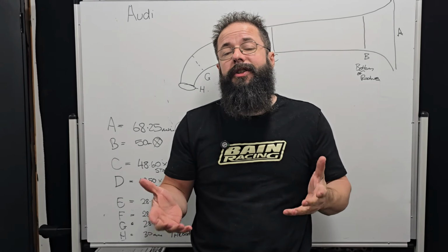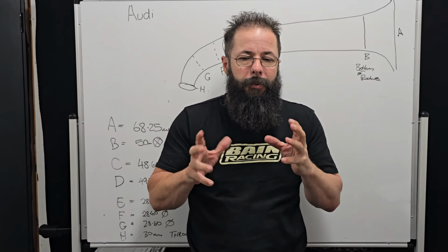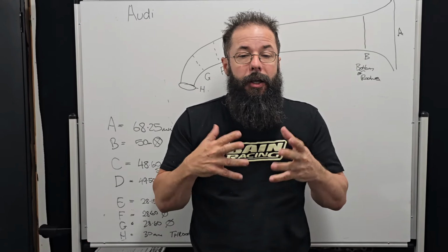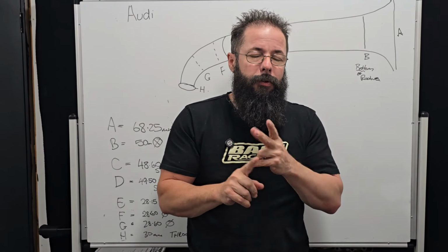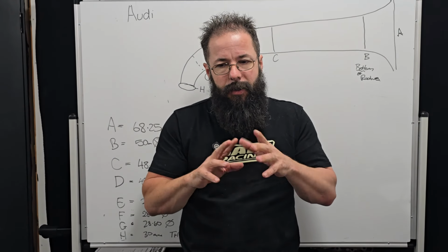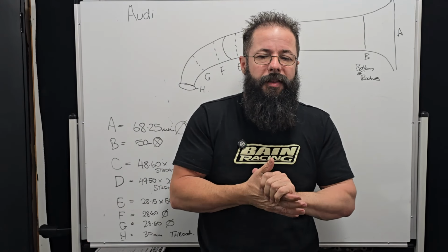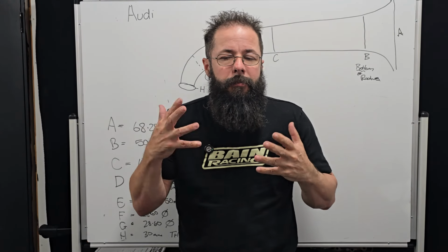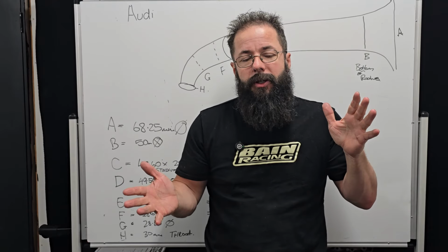All right, so we had a question about valve sizing and port sizing, and people asking how they know what size it needs to be. Obviously, we've got to look at our minimal cross-sectional area and a couple of other things, but they're talking about ratios of growth and stuff like that. And my response was, we've got to look at the whole primary induction length.